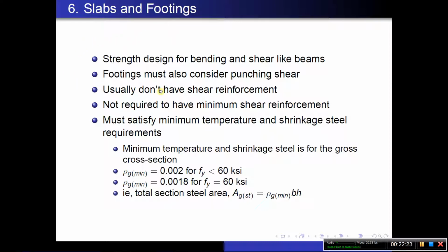Now, in slabs and footings, we usually don't have shear reinforcement. Oftentimes what we do is we design the footings and the slabs thick enough so that we don't need the shear reinforcement. And usually it's more efficient to do it that way, and most people do that.